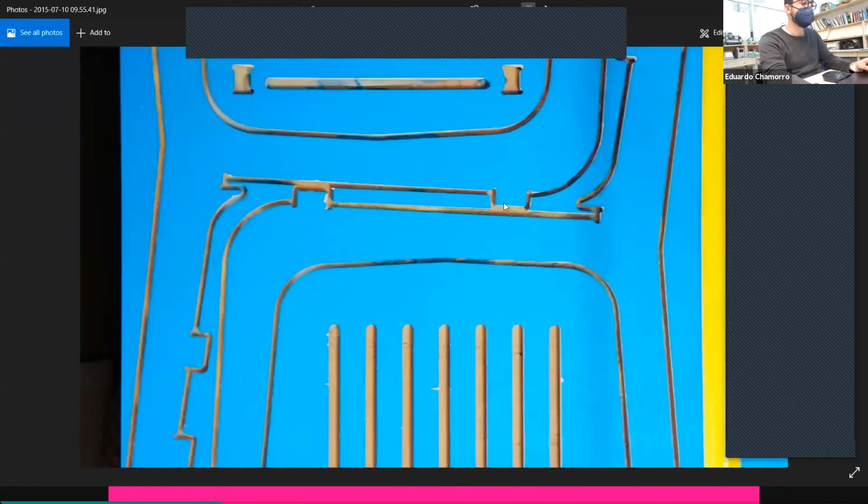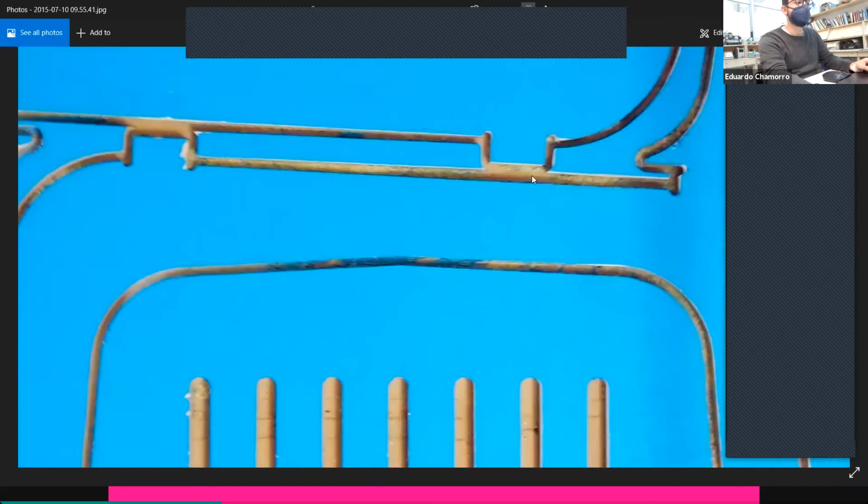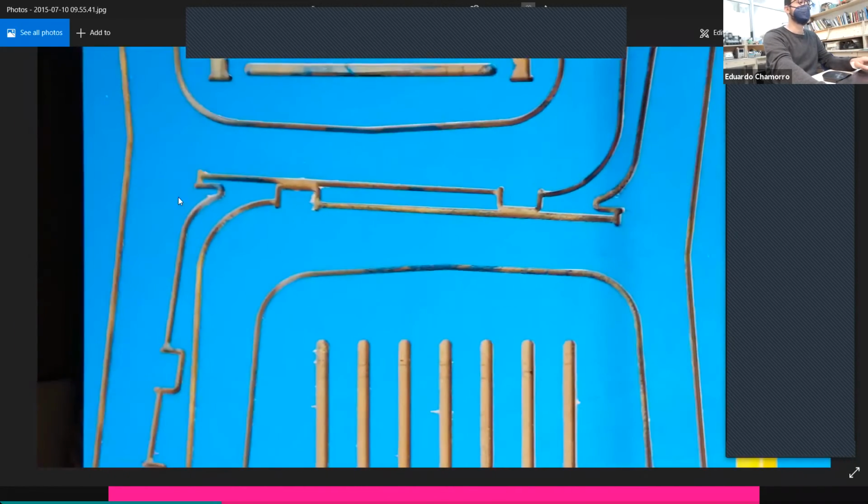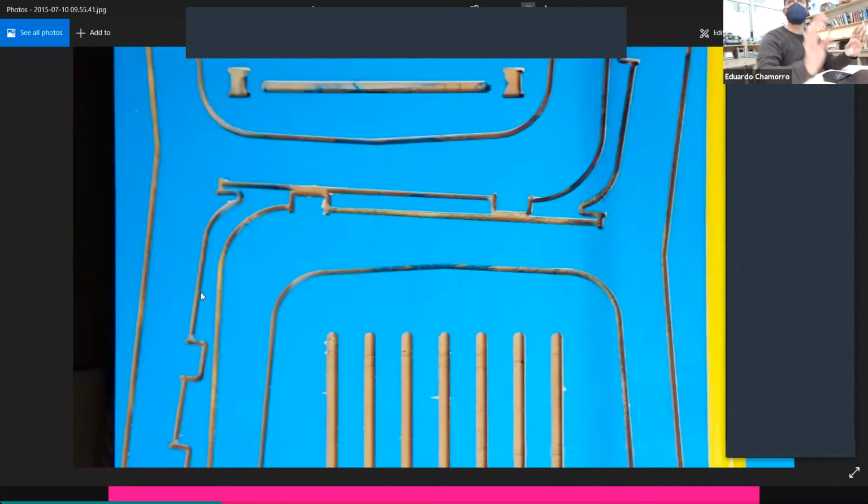Actually, you can see here, the line is a little bit offset. Why? I never leave less than 6 millimeters of space. This was cut with a 6 millimeter end mill. I just make a little offset so it never touches the same area again, just in case it doesn't damage the design. You can make really thin fits, but you always need a little bit of material.